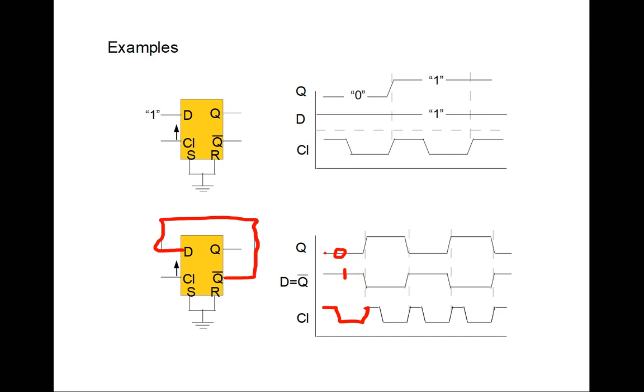So we transition the state from a 0 to a 1. Now the state is 1. Okay, now with Q going to 1, doesn't Q bar go to 0? So we get a 0 now for Q bar. And now D is equal to Q bar. The flip-flop ignores D during this region until we get the rising edge again.